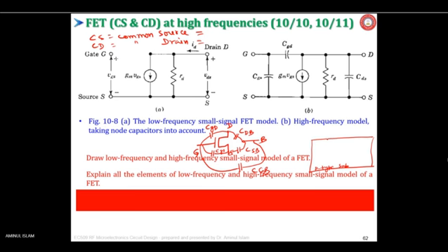So let us make this N plus and this P plus region. Sorry, N plus region, two N plus regions. Over that, silicon dioxide at the bottom. Then you have a polysilicon layer, and you have the gate.